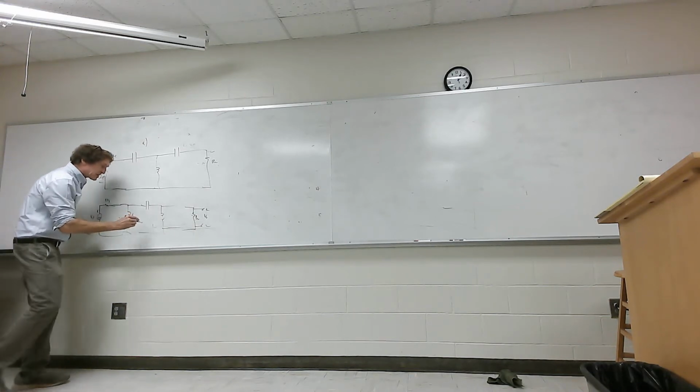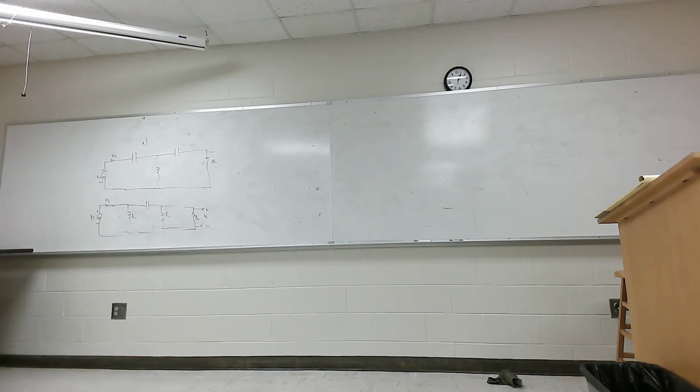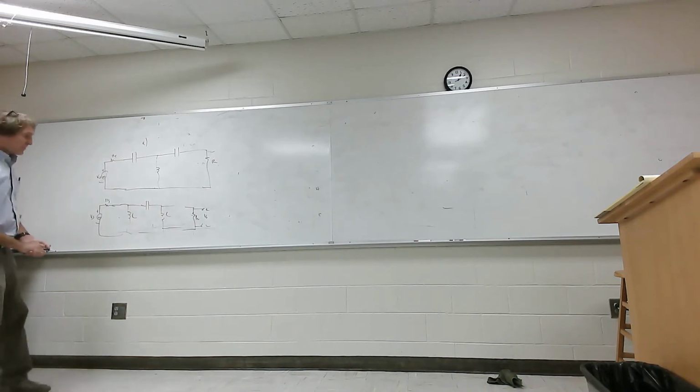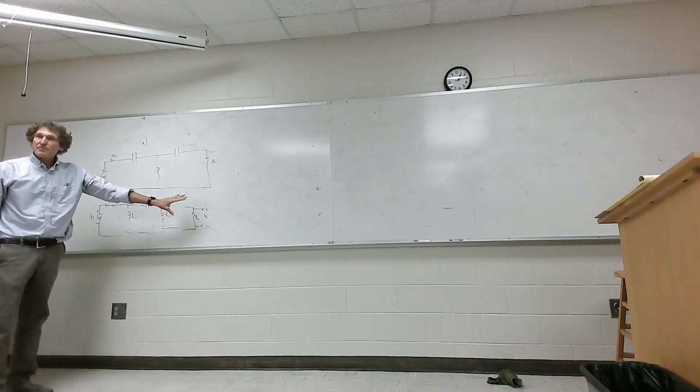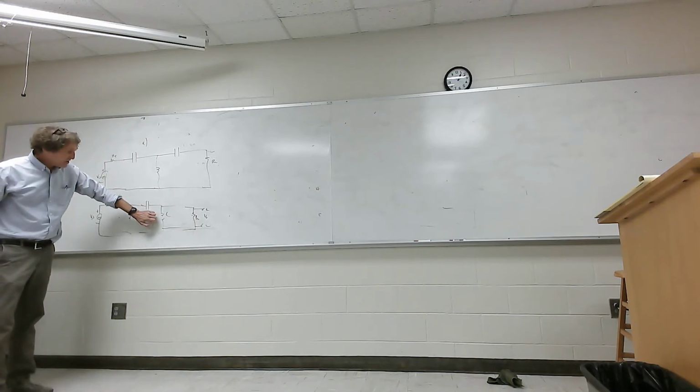Remember, that's an inductor, that's an inductor. There was one thing I told you about inductors that you should be aware of and not do. Remember what that was? Don't put inductors in parallel. Because at DC, if for whatever reason this was feeding the front end of a bipolar transistor, where there's a DC offset bias, you all know how there's self-biasing with resistor networks, this thing's going to look like a short.